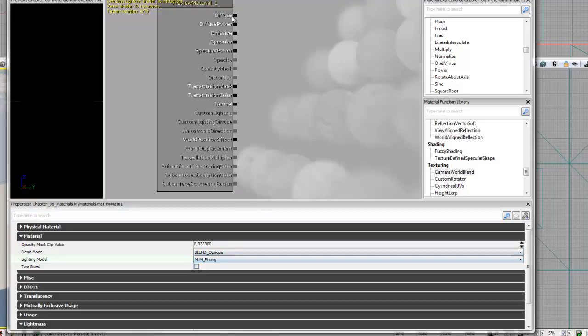So for Phong materials, you have a diffuse channel, an emissive channel, and a specular channel, and for specular and diffuse, you have powers that indicate how the spread of that channel is. You have a transmission mask, a transmission color channel, a normal channel that activates three-dimensional surface and bumpiness of your material, and you have a world position offset for your materials.